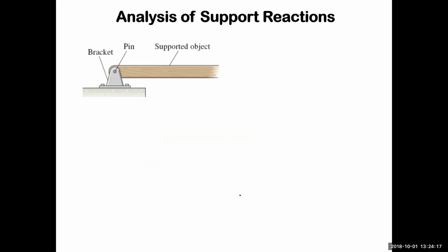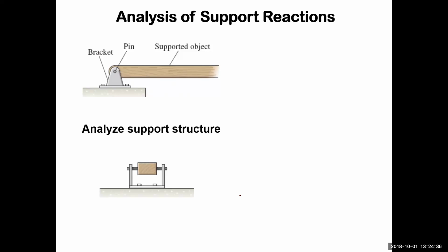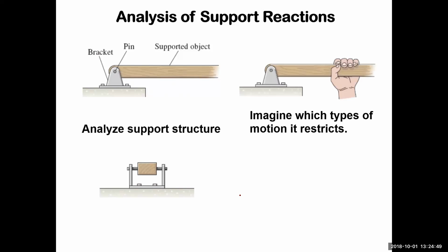But the question of these support reactions is a little mysterious the first time you see it. There's several types of reactions that we're going to have. A typical one in 2 dimensions is going to be a simple pin. A pin in 2 dimensions is going to, well, if you look at it on the side, it looks like that. If you look at it along the beam, it looks like that. It's not going to prevent any rotation in the XY plane of that beam.